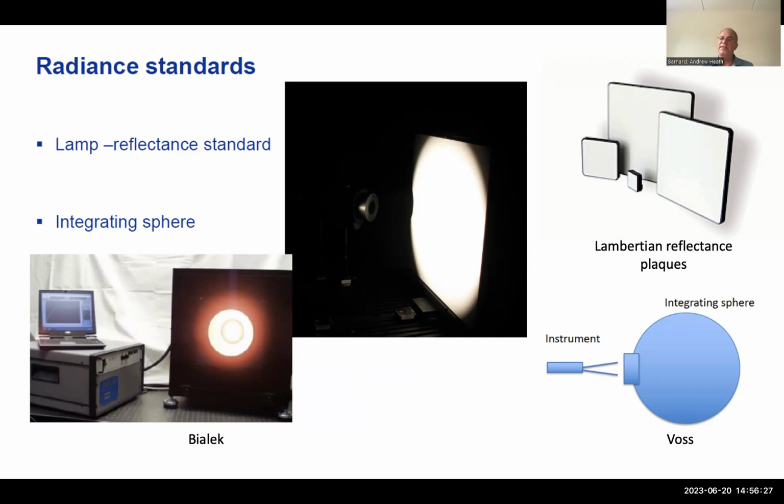Typically, even most reflectance plaques have a little bit of pattern in them. So it is good, every once in a while when you get a new plaque, to rotate it around, turn it upside down, left, right, so you can see if the actual value coming off the reflectance is the same value.